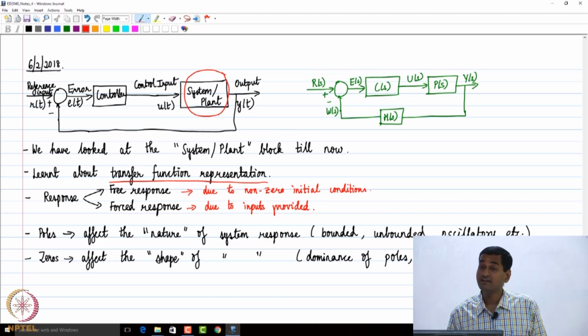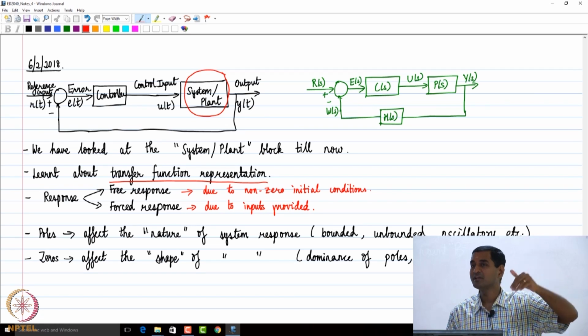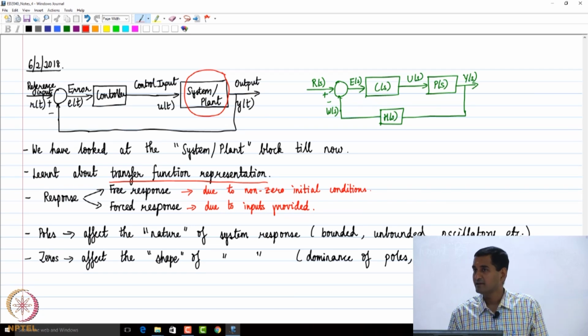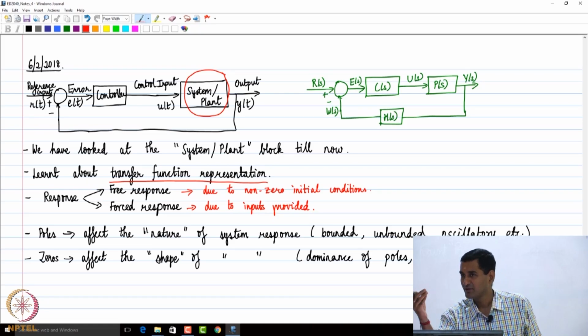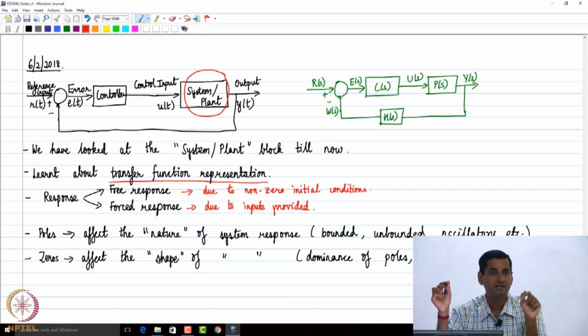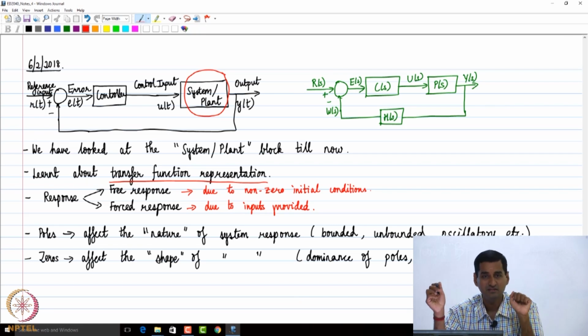And if we had what are called simple poles or non-repeating poles on the imaginary axis, then for maybe one input or one class of inputs, depending on the location of that pole, the output was unbounded. For all other bounded inputs, the outputs were bounded, right? If we had even one pole in the right half plane, the output is unbounded for all possible bounded inputs. And if we have repeating poles on the imaginary axis, then the output is once again unbounded for any bounded input. Okay, that's also something which we figured out, right?